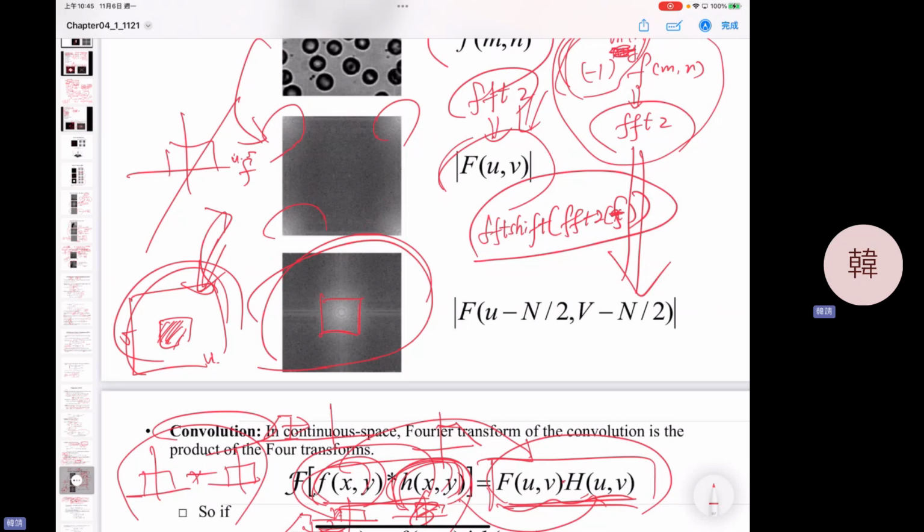Very good one. In the spatial domain, we will see the problem of this so-called ideal low pass filter, what result will occur. You just take this part and discard all the surrounding area. You multiply, because it's a constant one here and 0 outside. So you are going to apply a low pass filter. It's very straightforward. Intuitively, you can see only the low components will remain and the high part will be discarded, so it's called a low pass filter.